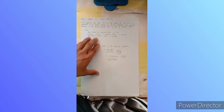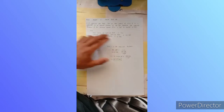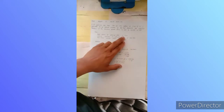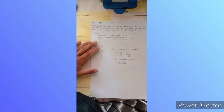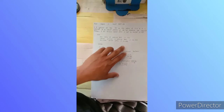So for number 5, a spherical gas tank has an inner radius of 1.5 meter. If it is subjected to an internal pressure of 300 kilopascal, determine the required thickness if the maximum normal stress is not to exceed 12 megapascal. So given inner radius of spherical tank, we have a radius of 1.5 meter. So internal pressure in the pressure tank, P is equals to 300 kilopascal. The maximum normal stress of 12 megapascal.